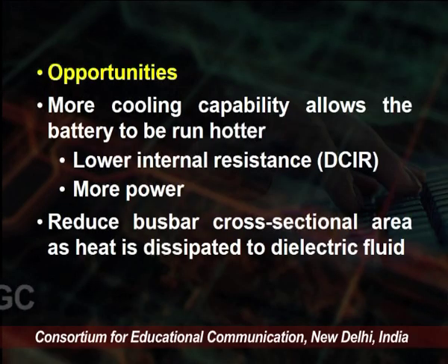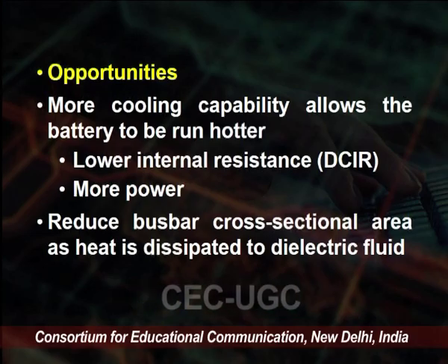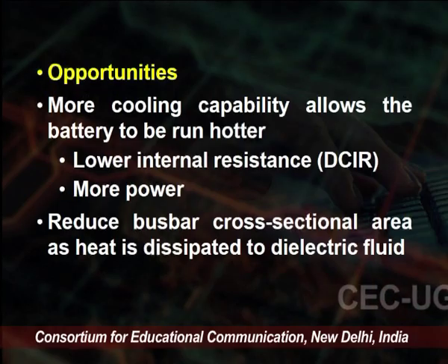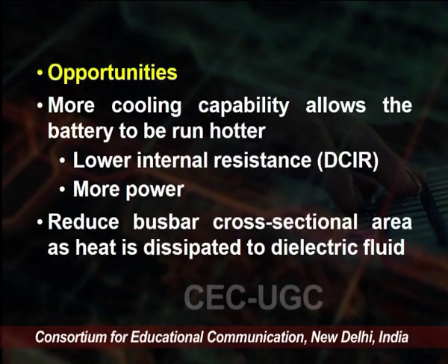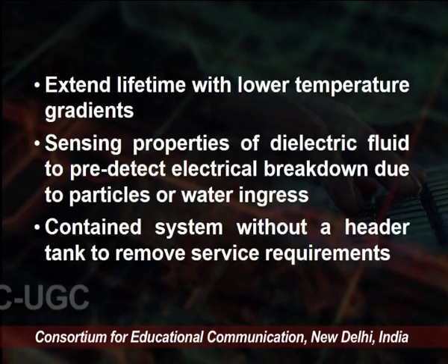So what are the opportunities? More cooling capability allows the battery to be run hotter. For that, low internal resistance and more power are required. Reduce the bus bar cross-sectional area, as the heat dissipates through the dielectric fluid. So extend the lifetime with a lower temperature gradient.